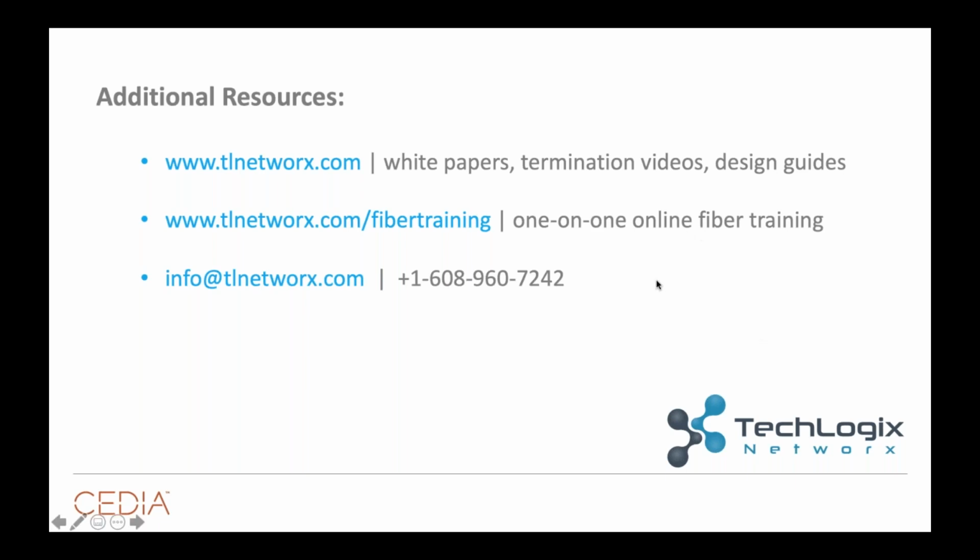All right, so next question, ARC and CEC. Can we send those over fiber? And the good news is, yeah, if you're using modern electronics, in fact, most of the fiber optic extenders, the HDMI over fiber extenders, they handle CEC. They even have ARC breakouts. That's one of the things that I'd recommend we take a look at on the TechLogix website. If you go to the extenders, you'll actually see that performance and those breakouts on the actual extenders themselves.